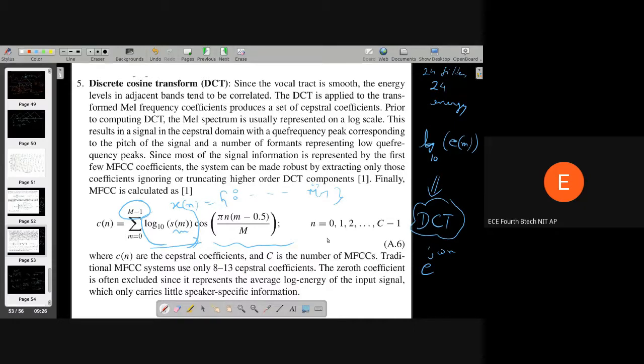There are benefits of taking the discrete cosine transform. You could also have taken the discrete sine transform, that also exists, but we found that the discrete cosine transform gives better results compared to the discrete sine transform and other similar transforms. It behaves in a more compact manner, and it has been successful in many applications. We also avoid generating unnecessarily complex numbers, because our aim is not to do Fourier analysis of these energies. Our aim is only to represent them in compact form.